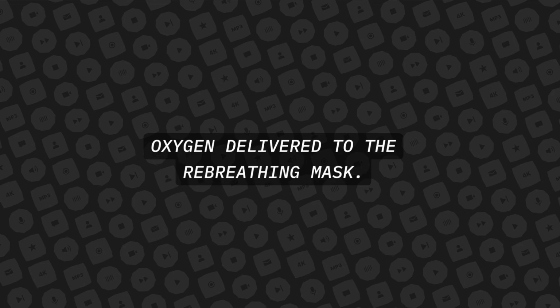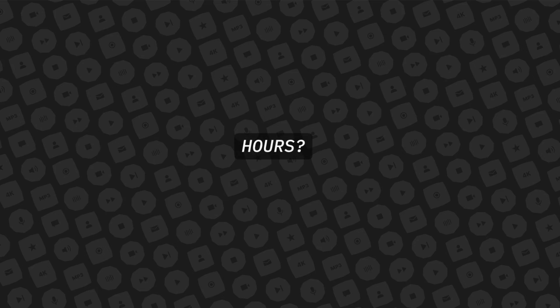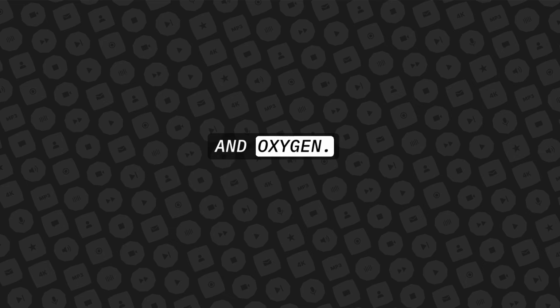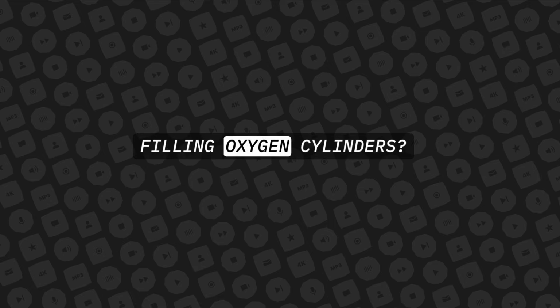rebreathing mask. What must be done if an oxygen system has been depleted and not recharged within 2 hours? It must be purged with dry nitrogen or dry air and oxygen. What safety consideration must be observed when filling oxygen cylinders?